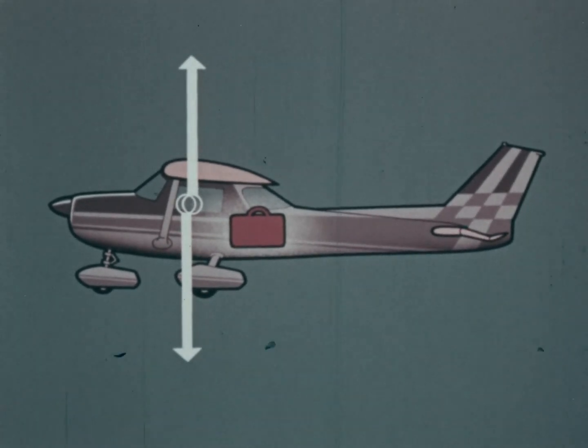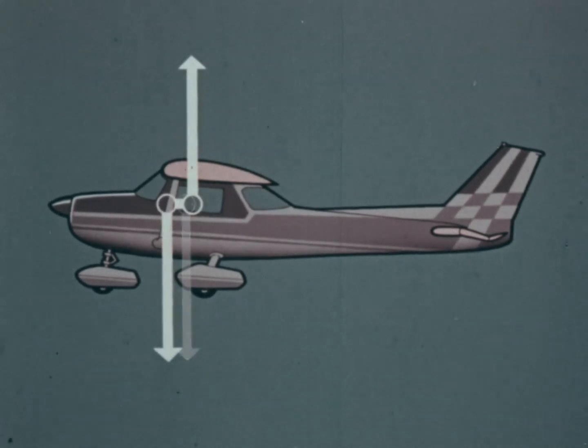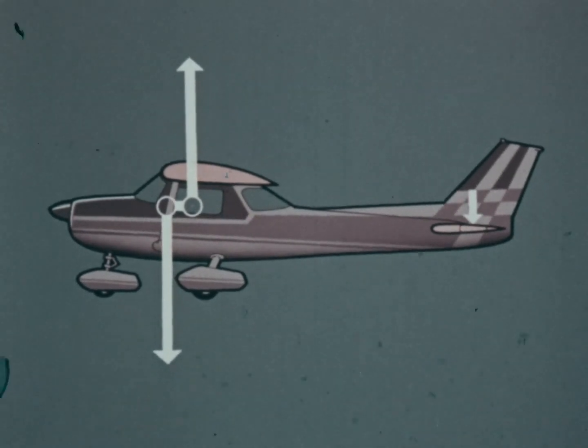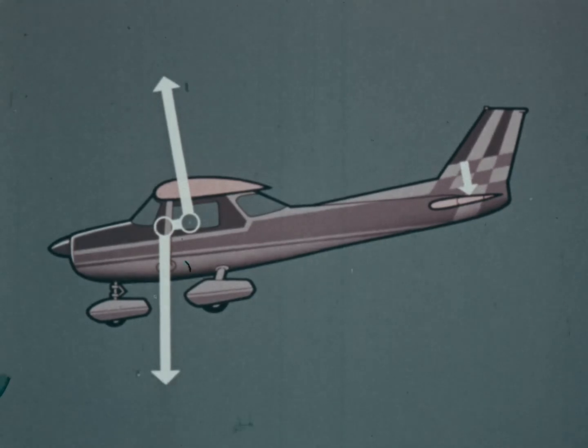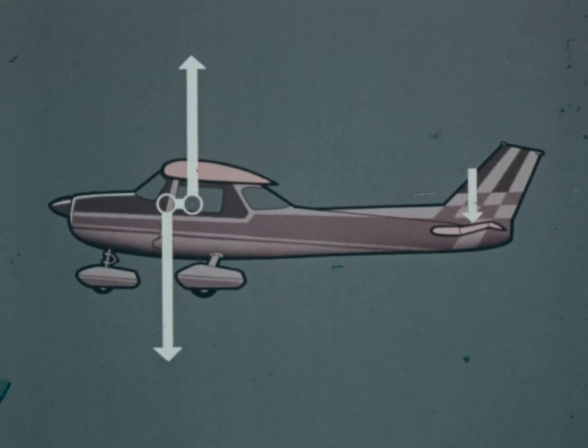The airplane can thus maintain level flight despite the fact that the center of gravity is misplaced, provided it is still within the design limits of the airplane, and without the pilot having to hold the airplane level manually. In the same way, if we need to increase the download on the tail, we can use the trimmer in the opposite sense.